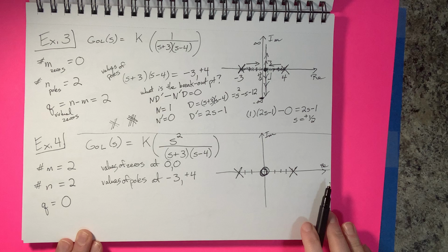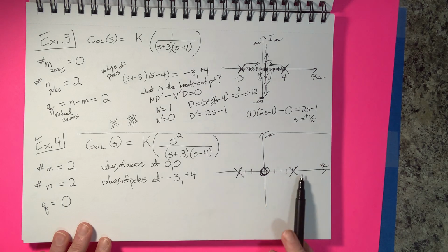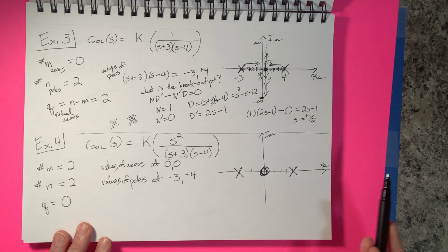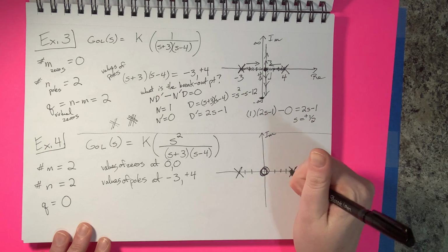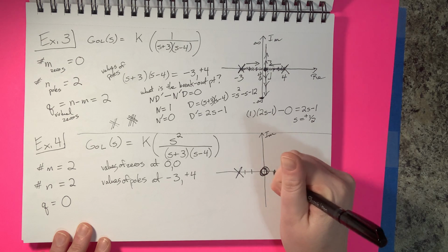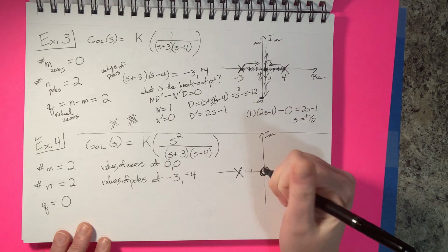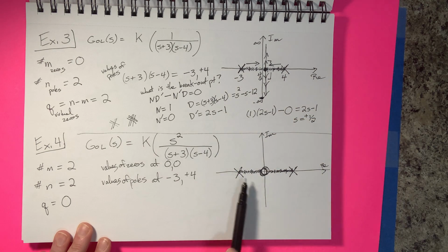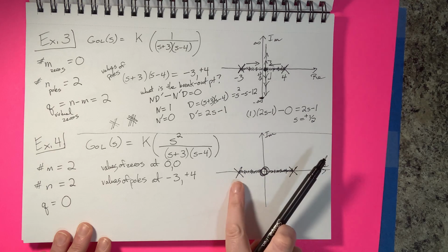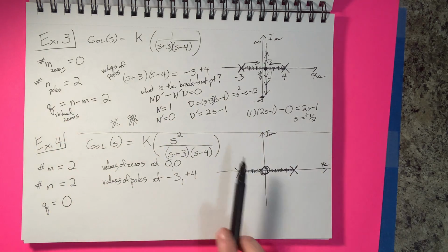All right, so let's apply the real axis rule. Surprise, surprise. It's very handy when you have anything on the real axis. So we move our pen across here, and we just fill in this branch because it's odd past this first value, but then we add 2 poles, and it's still odd. Okay, and then if we look past here, we have 1, 2, 3, 4, so it's never again going to be odd looking rightward.